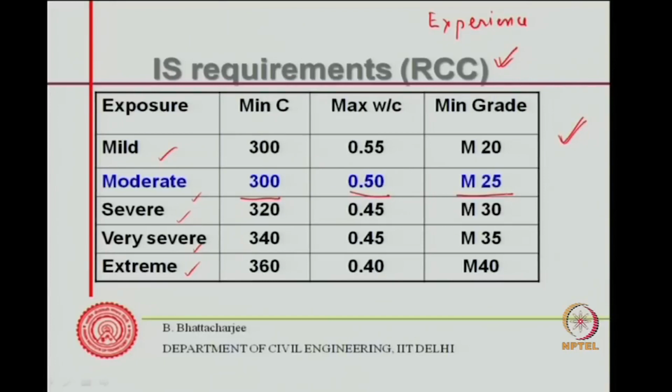So, we are doing design for M25, therefore these are the relevant ones: this is the maximum water cement ratio permissible and this is the minimum cement content permissible.